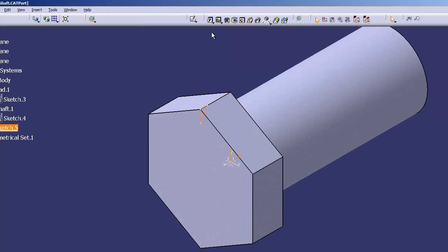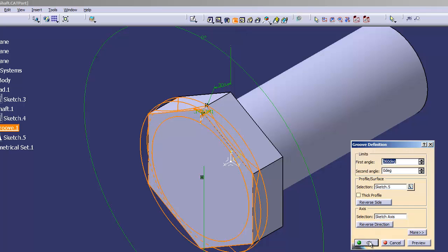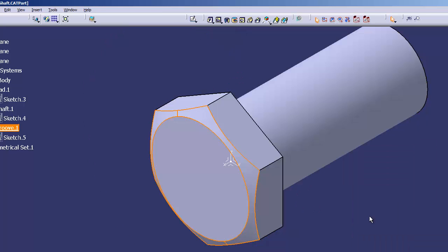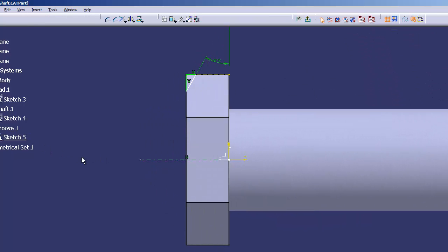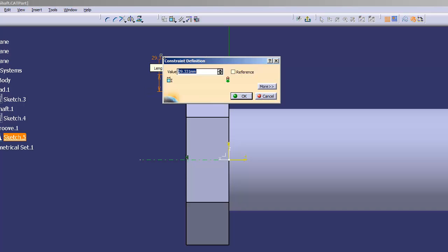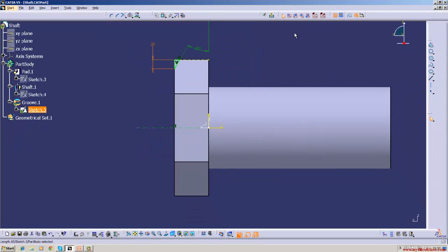Click here and you may use the groove command. See. Groove. Normally the groove portion will touch this, that we have to calculate and see, or by trial and error also we can do it. This is 30, this and this side, it depends totally on this side. You increase this side, or it will be cosine of 30 degree angle divided by this hexagonal length. That is how we can calculate, or we can reduce this side to get the circle exactly tangential.